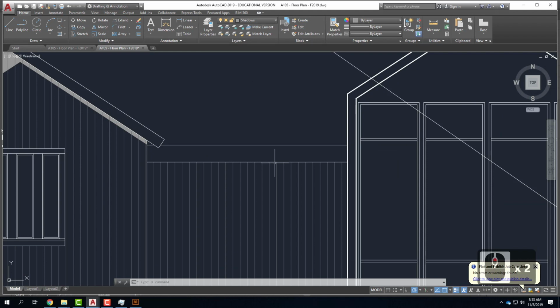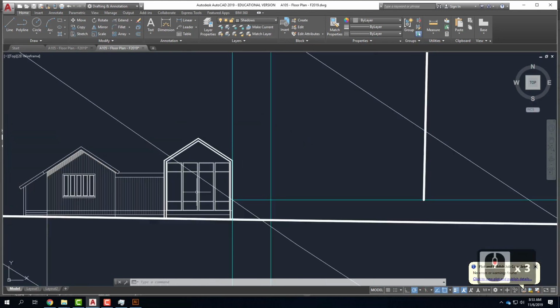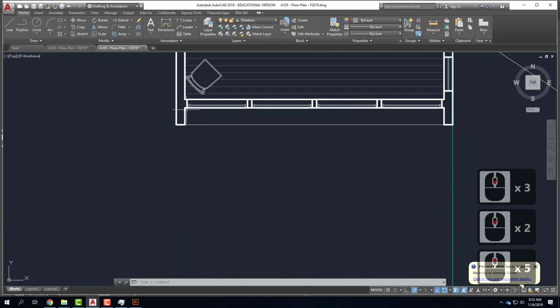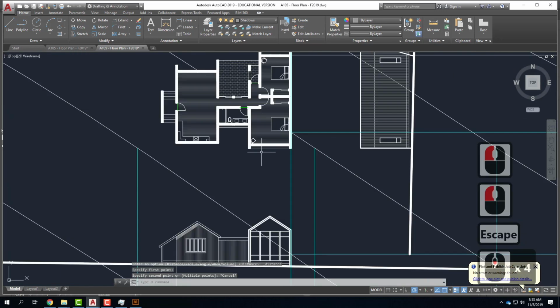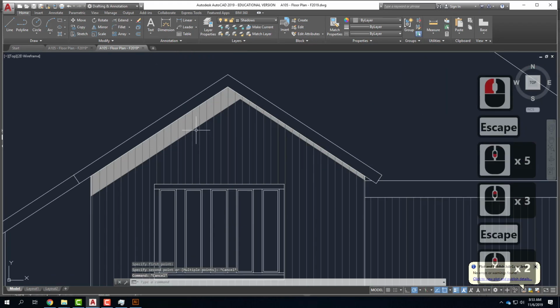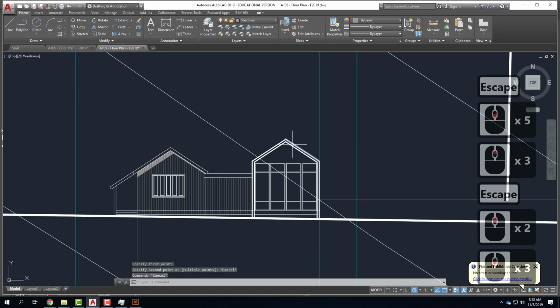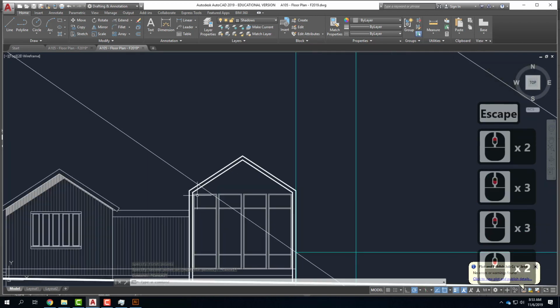This shadow here would be pretty easy. It's the same because it's just an offset. If this overhang was a foot, I'd go down a foot and I'd fill that one in. This one's a little bit more complicated. I need to know how far this distance is. It looks like it's a foot too. Yep, that one's a foot too. So that makes life easy because I can essentially copy this shadow here onto this. The only difference is there's a shadow running down this side because of that little wing wall.